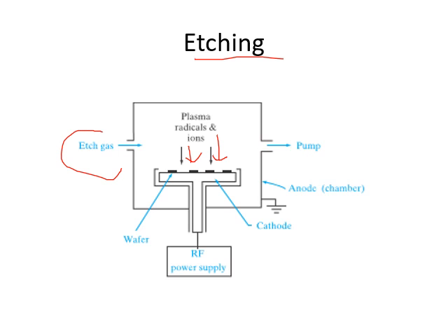We use some hydrofluorocarbons as the etching gas also, which helps in the etching, and we maintain the potential difference so that the kinetic energy of the particles being bombarded will be maximum. So here we have an RF power supply. The anode and cathode are maintained such that the voltage difference will be around 100 volts.